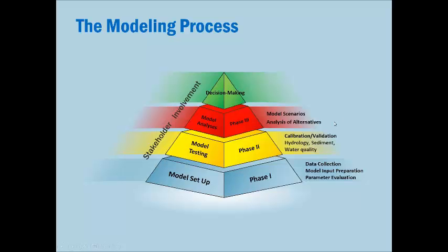You can then move on to performing model analyses. Modeling scenarios on the watershed, proposing changes in order to improve water retention or water quality conditions on the watershed, simulating that, and then identifying what level of analysis or what level of alternatives you might want to consider in terms of following through with implementation. So this provides information to the decision-making process as to what if things change on the watershed, or how can I change things to make water quality improvements, or to meet water quality standards, or in developing a TMDL and distributing that load allocation to the various contributing sources.